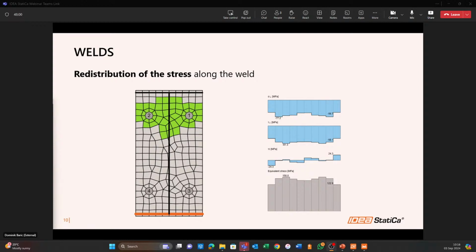Calculated values at the most stressed weld element are used directly for the checks of the weld component. This way, there is no need to reduce the resistance of multi-oriented welds to unstiffened flanges or long welds.